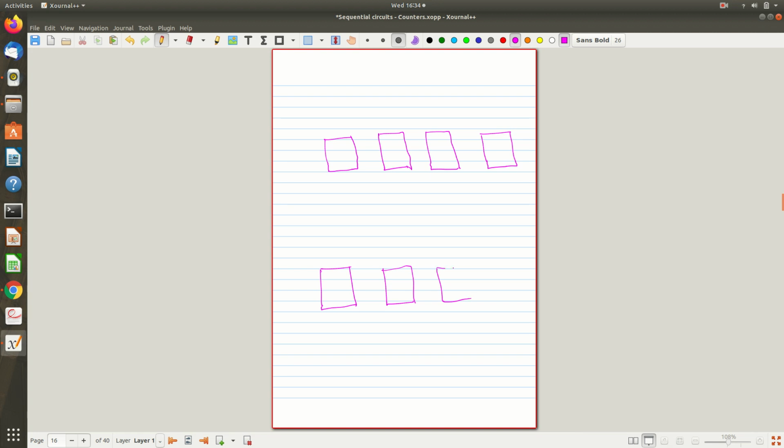In the background, for this flip flop you can use a D flip flop or a T flip flop, anything, and how the construction varies from one flip flop to another we will see. Synchronous counter means this is your clock pulse, and the same clock pulse you are applying to all the flip flops. Maybe this notation means positive edge triggering, right? So this is what we call a synchronous 4-bit counter. The flip flop can be anything, but the connection will vary, that we will see.